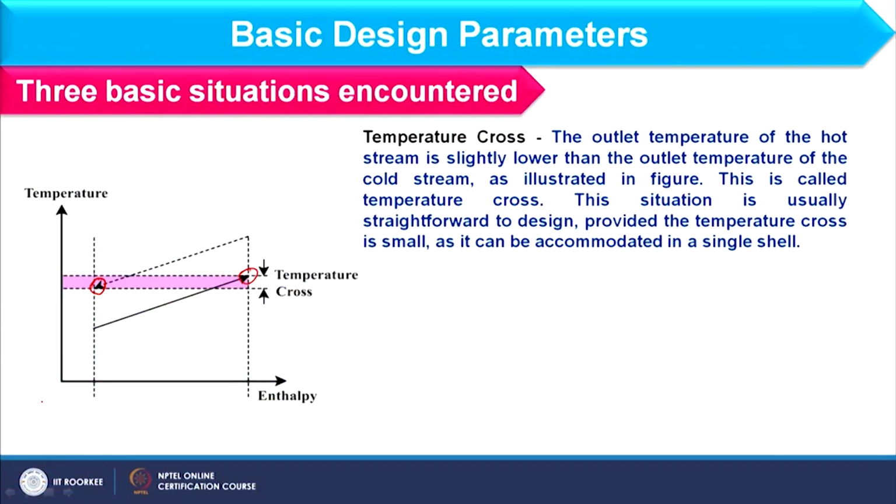In that case, if I consider counter current flow, or if you focus on this diagram, at every point cold fluid is lesser than the hot fluid. Okay. So, feasibility is maintained, but only as far as counter current flow is concerned. Okay. Now, if I consider a 1-2 shell and tube heat exchanger and the hot fluid is available in the shell side.